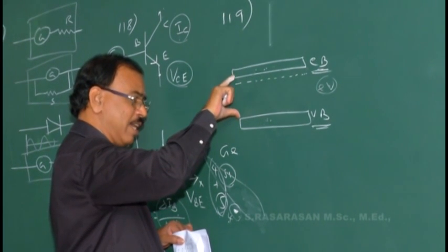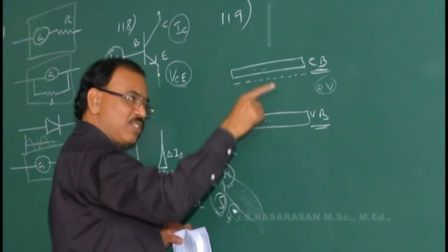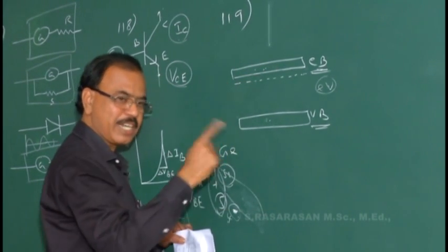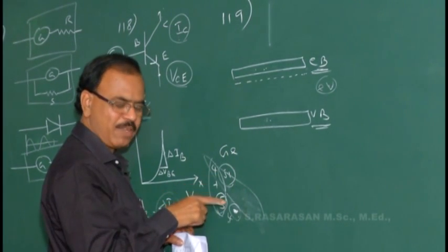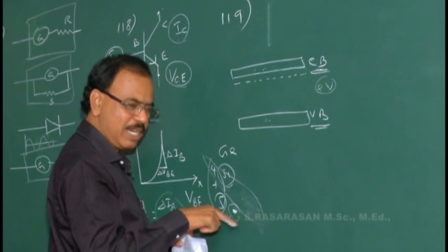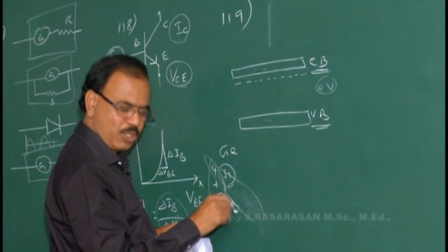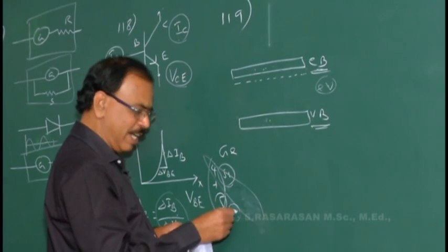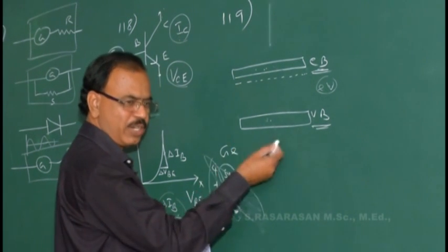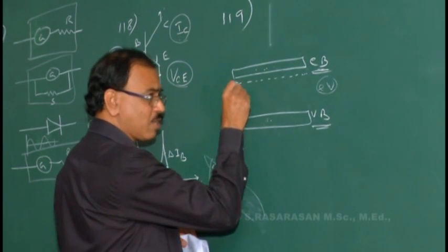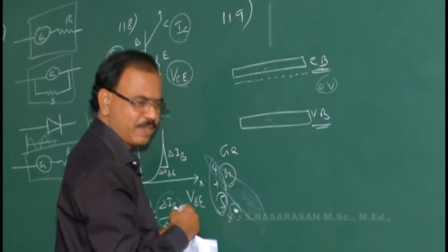It was 0.7 electron volt, now it has reduced to 0.5 electron volt. With the forbidden gap reduced, electrons can easily cross over the gap or jump, and conductivity increases. So in n-type semiconductor, by doping pentavalent impurities, free electrons are contributed for conductivity. These are called donor atoms, donating one electron for conductivity. This electron contributes one energy level, which lies just below the conduction band. Thereby the forbidden gap is reduced and conductivity increases.